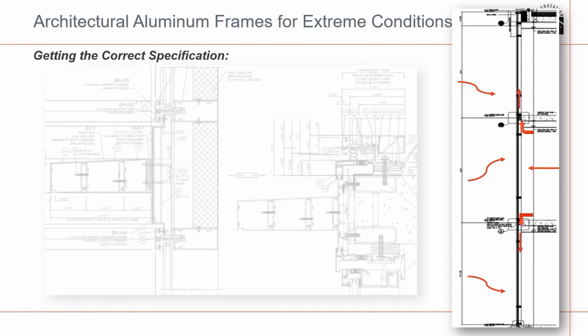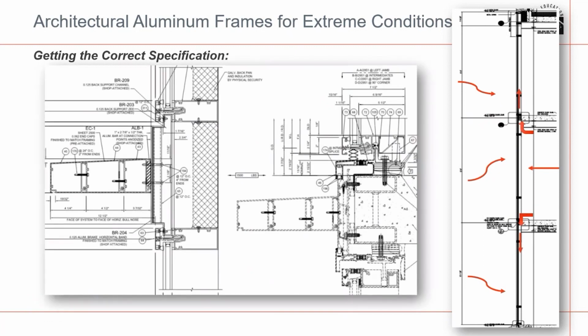Here's an example of a typical curtain wall that you see here on the far left. And in this curtain wall, sound generated on one floor can reverberate up through the mullions past a floor line to the next floor. Now, this might not be that big an issue in a typical office building or commercial building, but when you move to a high-rise multifamily project, sound moving from one floor to the next is a big issue. So in a case like that, you might want to consider using window wall systems.